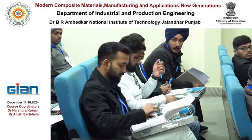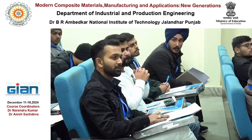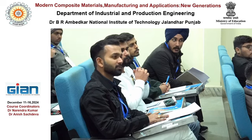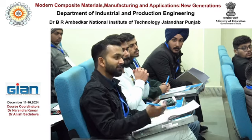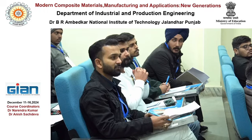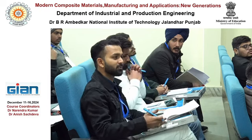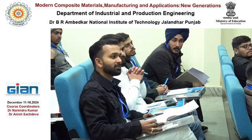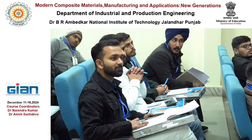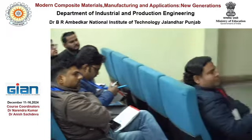Another question is that you said that complex structures can be made through composite manufacturing. But if we see the traditional composite manufacturing process, it is very difficult for us to get the composite part. If we want to manufacture a complex composite, then we will have to do post processing after the manufacturing of the composite panel, and that is very difficult to do in the composite. So how can complex shapes be made of composite material?